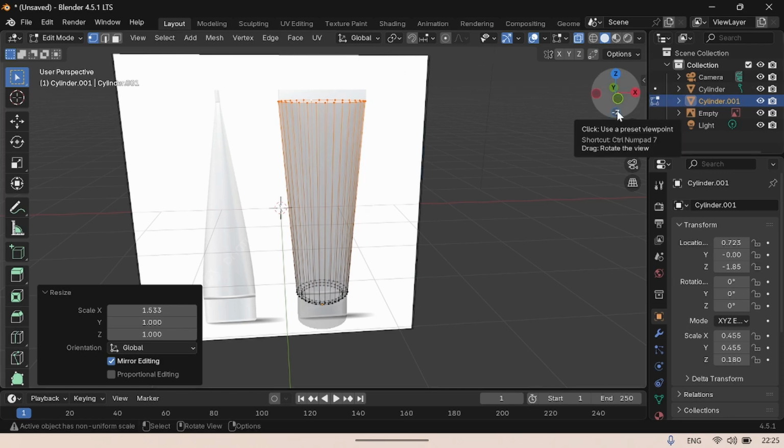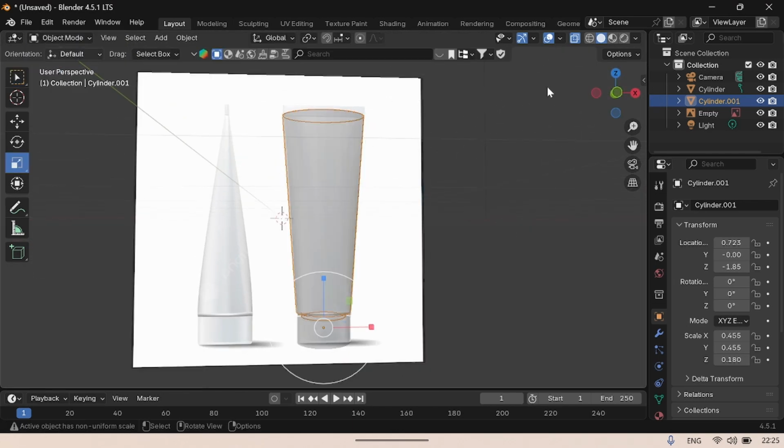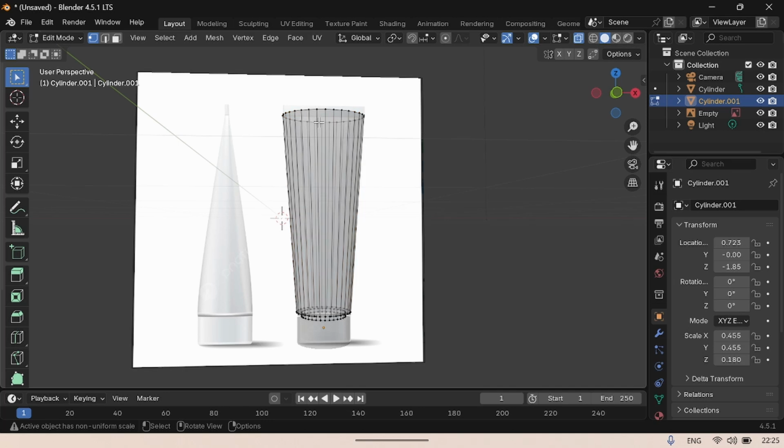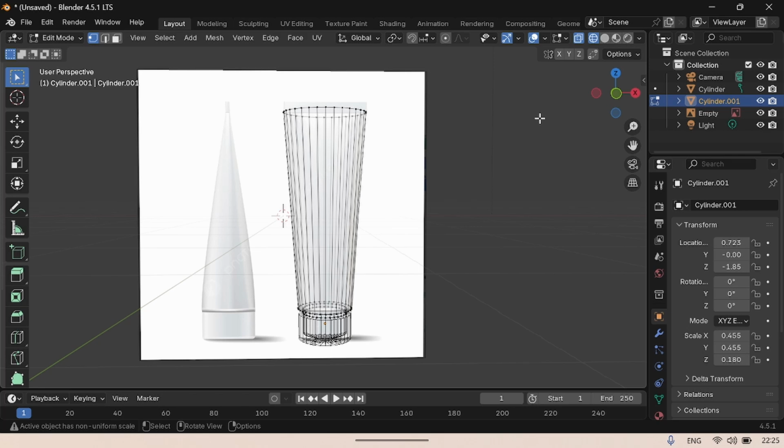Okay, let me see where. Okay, we are going to go to edit mode like this, so you can see like it's fitting perfectly. But now I want us to have these tapered ends. So what we do, we go back to edit mode and select the top vertices like this. Then going to scale it this way along x-axis.